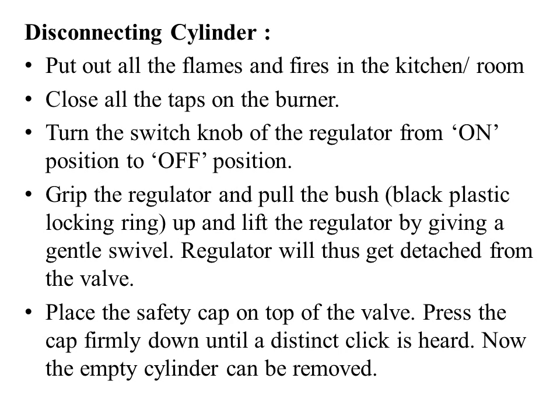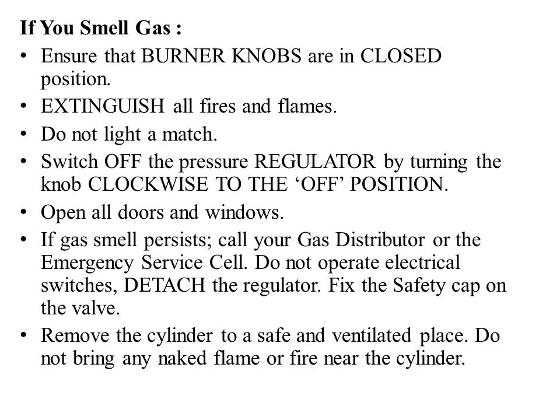The next step is we need to place the safety cap after the regulator has been removed. The safety cap that is provided with the cylinder should be placed on the valve. Now, of course, we have to press the cap until a click sound is heard. Now the empty cylinder can be removed. Even when we are not using a gas cylinder or we have to just take it out, this is the procedure that has to be followed.